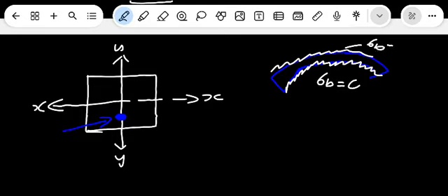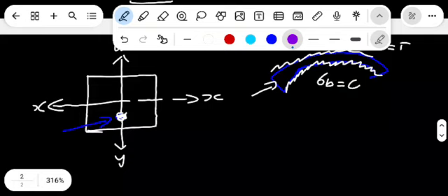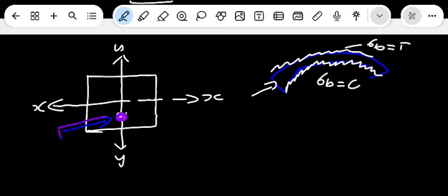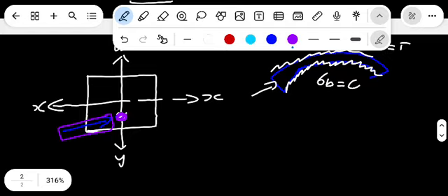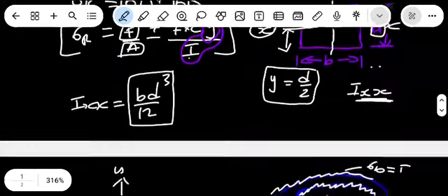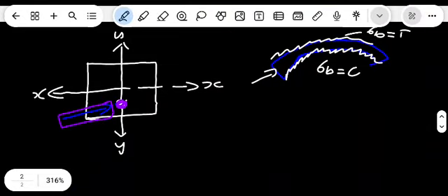The bending stress there will be what? Tensile, whereby it's positive. But there is also a force applied that is causing a direct stress acting there. What is the type of this? It's compressive. So compressive will be what? Negative. So now since this is a direct stress, it will be compressive.